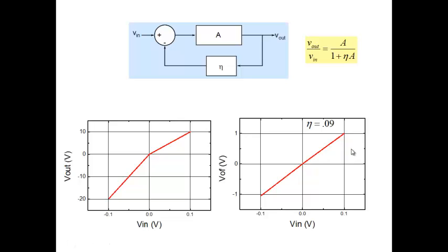But now if you think about it, this A is still nonlinear, right? So if I feed in a pure sinusoid here, I will get a pure sinusoid here, correct? Because it's linear. Let's say it's perfectly linear. But the amplifier A is still nonlinear. I've not touched the amplifier. So what will happen at the input of the amplifier then? Can it be a pure sinusoid? What will it be? The amplifier will still distort, right?